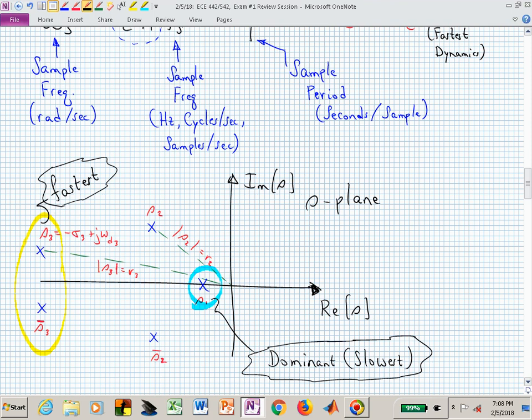I'm giving you the answer, actually, but here, let's say, what's the order of this system? This is a continuous time system. It has a transfer function, capital H of S, and that H of S has poles associated with each of these x's. What's the order of that system? And now it's as simple as how many x's are on the board in this portion of the screen.